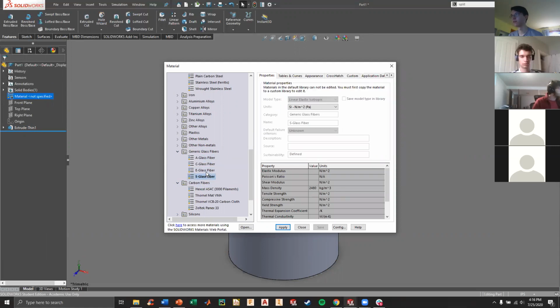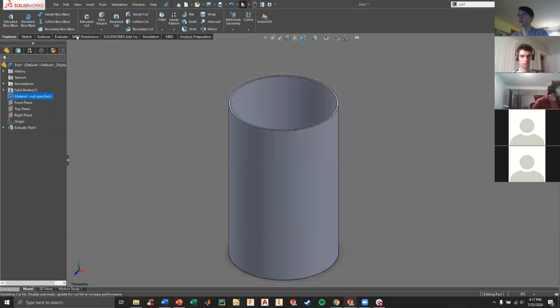they don't have a lot of the material properties that you need, because carbon fibers and glass fibers are not linear. Well, first of all, they're not linear. They're also not homogeneous, whatever the word is. There's some word for it. So they have different responses to stress in different axes that you force upon them. So you can set this, and mostly you'll just get the mass out of it, which will be the only useful thing.